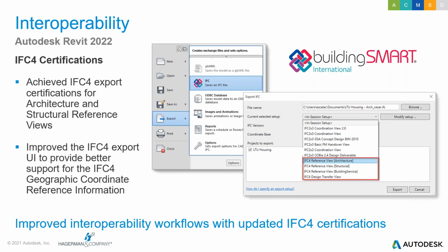IFC property set definitions and the associated Revit shared parameter definitions have been updated with the latest IFC4 PSDs of version 4.0.2.2, partial update from the scope of 1.2 MVD. So this significantly improved the performance of linking in some IFC files containing elements with many parameters.